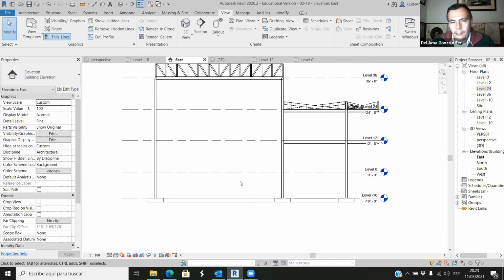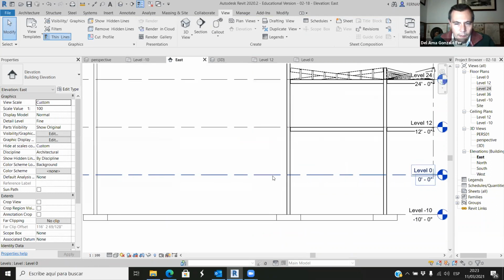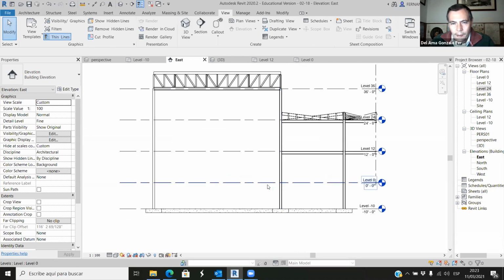in this east elevation, we need that span because this is the basketball court, but the basketball court starts here on level 0. So this is a basement. Do we need this span in a basement? We don't. And if we don't need this huge span, we better create a different structure, because creating elements with long spans is very expensive. So it's more convenient to create columns here.